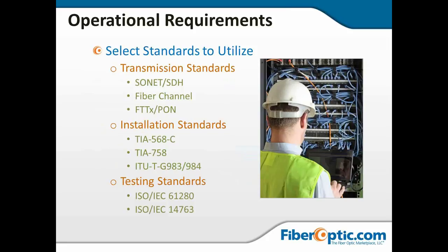Then we need to select the standards. We need to look at transmission standards for the protocols. Again, SONET or SDH, fiber channel, passive optical networks. We need to look at the installation standards. In the United States, we might look at EIA-TIA 568C and 758.